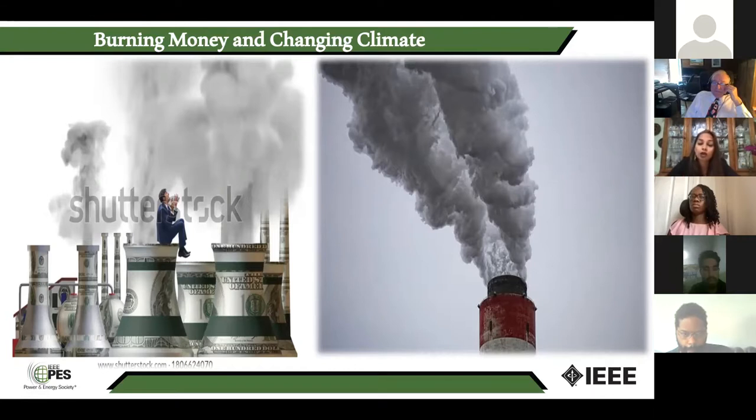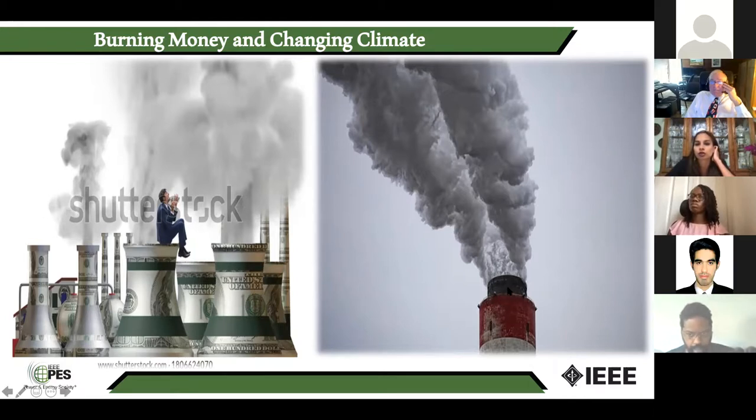But the disadvantage of this ESP is that it cannot be charged until your flue gas temperature reaches approximately 130 degrees centigrade. That's to avoid sulfuric acid formation at low temperatures, which is possible because the pollutants contain sulfur oxides, and those pollutants can cause acid formation. You can always see at the tips there are oxide formations and corrosion happening.